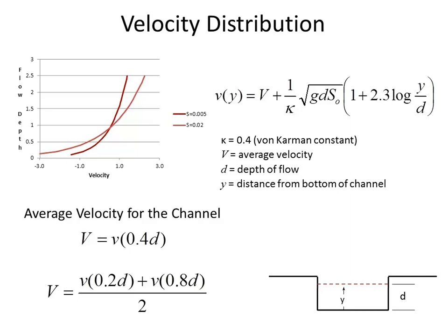That's sometimes used when you're taking physical measurements of velocity and want to estimate the average for the stream, because there's a velocity profile, even when there's turbulent conditions, there will be a pretty pronounced velocity profile. So I don't think you'll actually solve any homework problems that ask you to calculate this velocity distribution, but it's important to note that it's just a mathematical approximation of that velocity front.